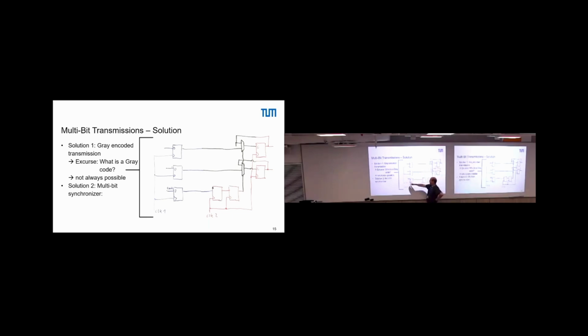So we can put some synchronization on an enable signal. If we send data here and receive them on the receiver side, then we only synchronize the enable signal, and we ensure that the data here are stabilized when an enable signal has propagated through the receiver clock.